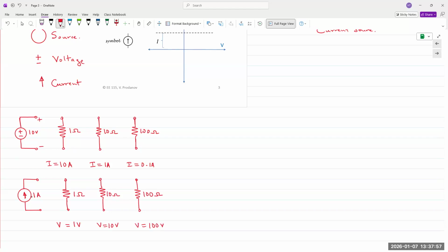What if you change it to a 1 kilo ohm resistance? How much voltage would you expect? 1000 volts, absolutely. The reason I bring up that example is because 1 kilo ohm resistors are some of the most common resistors you will use in the labs. But do you think any of these power supplies go up to 1000 volts? No. So real life power supplies might go up to like 20, 25, or these ones go up to like 30 volts. Okay, that's the max limit.